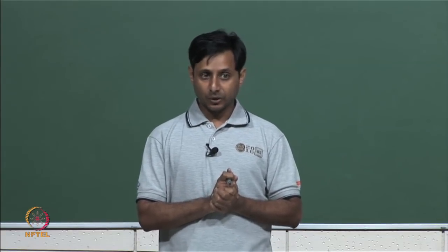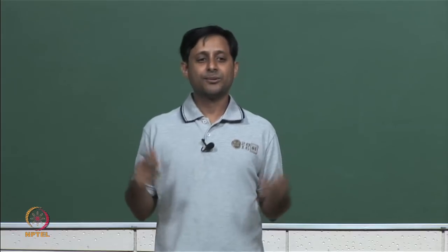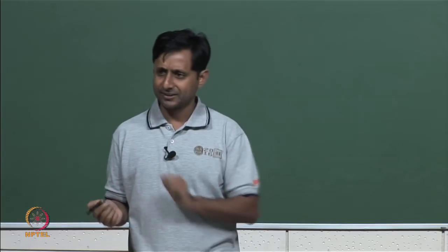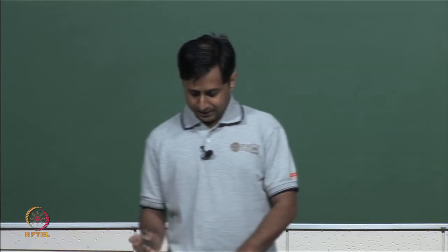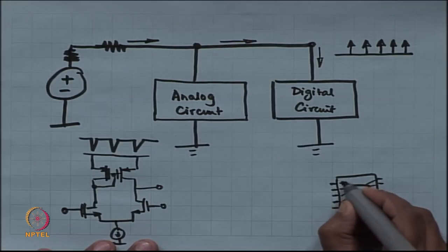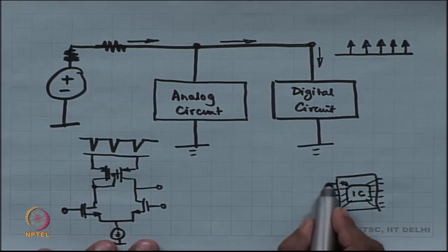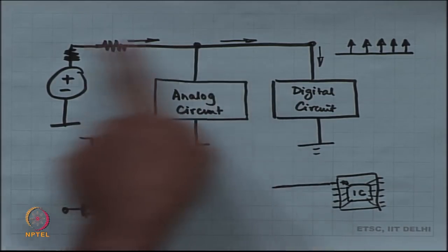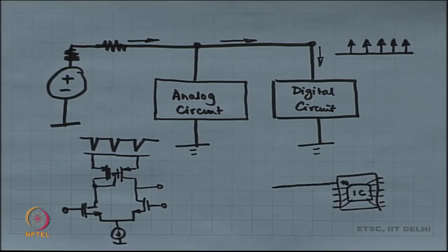So, if you have a thin wire, what is it going to present? It is going to present inductance. So, these wires present inductance. Then this power supply wire is inductive already. This is already an inductor that goes through a long wire, which is again not very thick, all the way to the power supply, and that is also inductance. So, everywhere you have inductance.